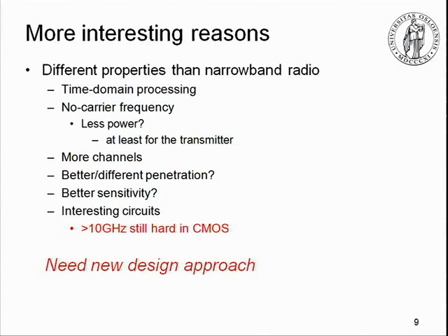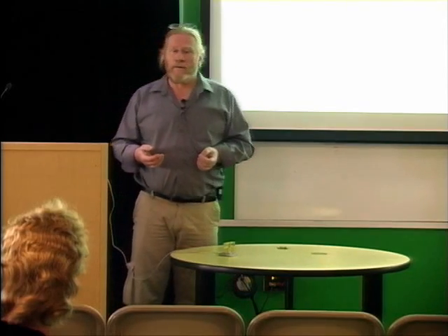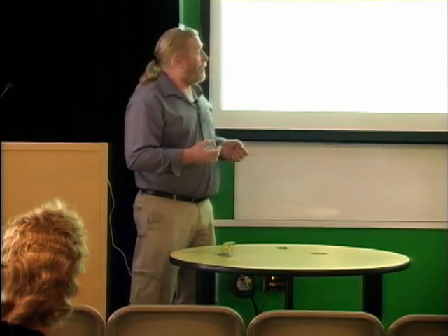I can do other different things, which are not that intuitive to see. One of the problems with traditional radio is interference. I have a reduced number of channels, usually like 16 or 8. On Wi-Fi there are like 11 or 13 channels, depending on where you are. And after all, if you look at Wi-Fi, it's actually 3 or 4 channels non-overlapping. So it's very few channels, and the number of channels is actually a problem. With these kinds of time domain systems, I can make 1,000 channels. It takes a little time to show you why, but there's no free lunch after all. If I make a large number of channels, my penalty is the bandwidth, but that's on each channel.